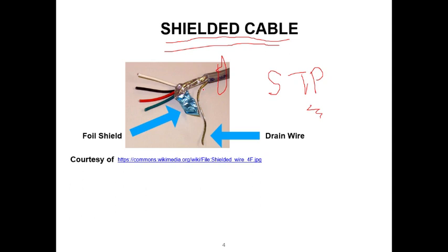Notice here we have a drain wire, or sometimes called the ground wire or a drain ground wire, that normally you're going to connect to a clean, note the word clean, ground, which may not necessarily be the facility earth ground, which is usually noisy.